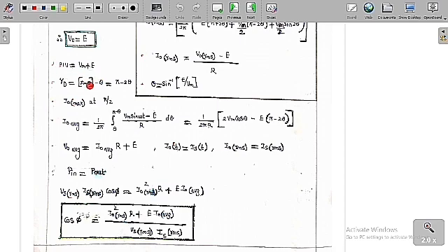I have already told you that just now. And the conduction angle of the diode is the angle for which the diode is conducting. It is conducting from theta to pi minus theta. So the difference of angle is pi minus theta minus theta, which is pi minus 2 theta. Only for this amount of angle the diode is conducting. And we are going to get the maximum value of the current at theta equal to pi by 2.